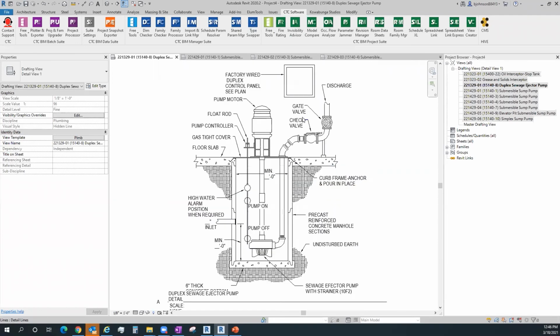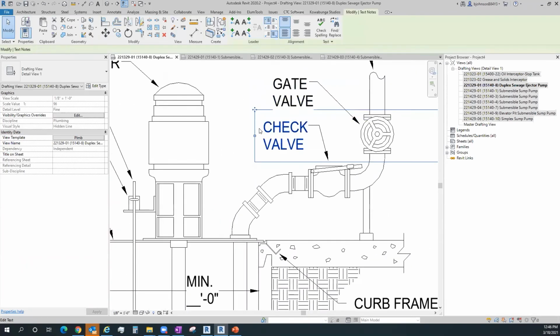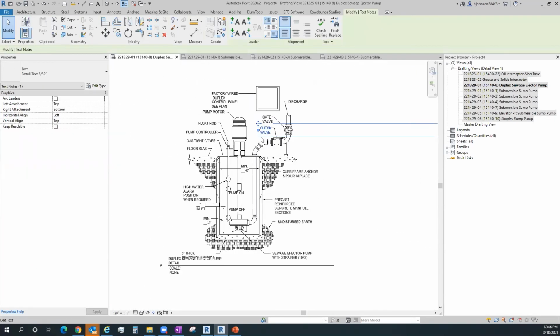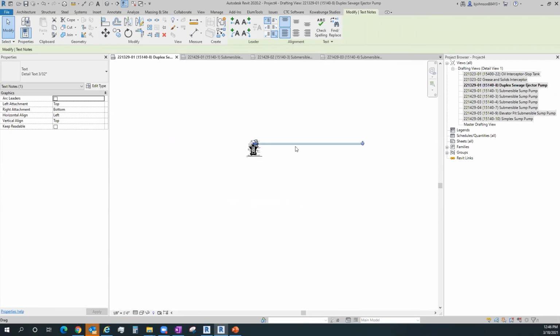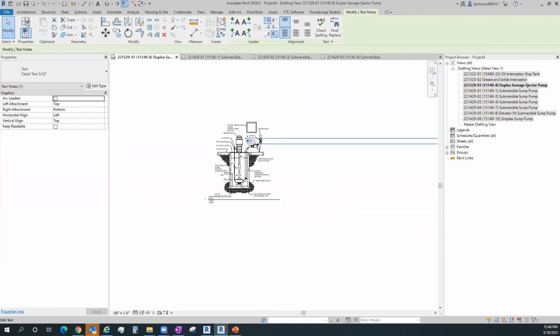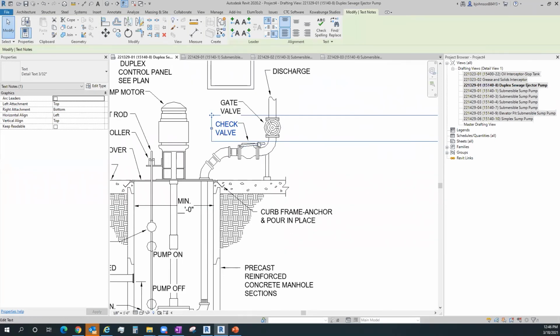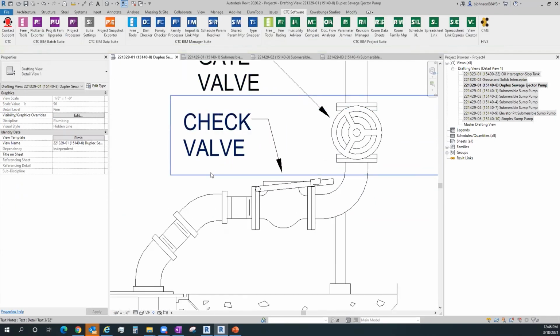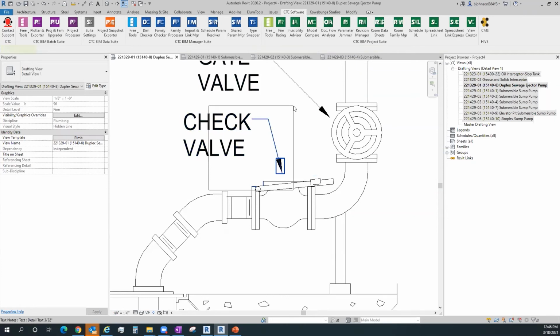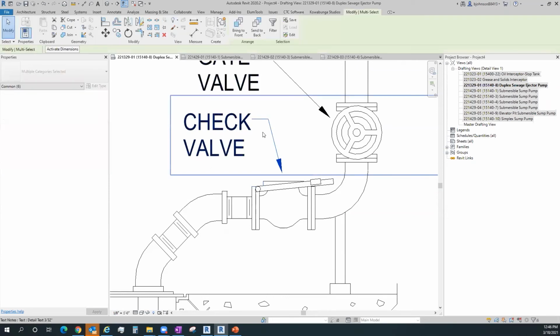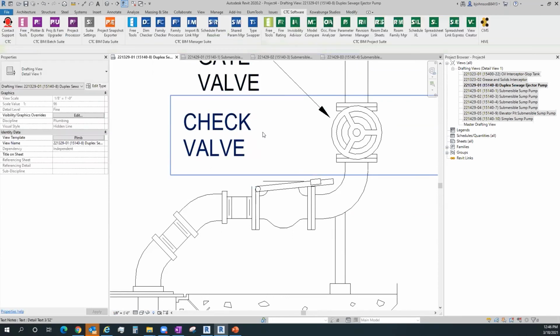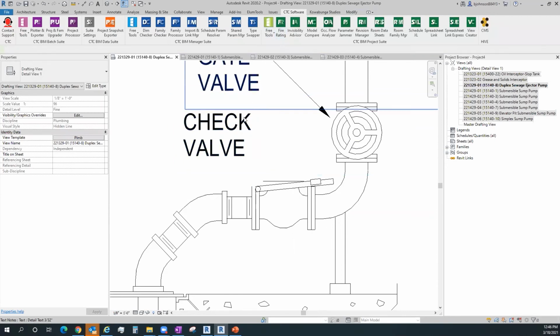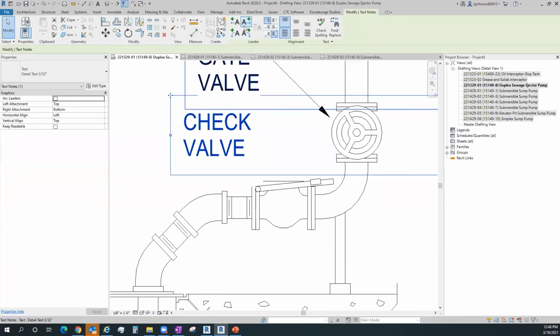So the last things I need to do on each of these would be on each individual component of mtext. I would go back and make sure that this large, long window that I typically despise, stretch it all back to a normal size, or just copy and paste it into a new piece of text, move it back where it goes, and then go find my line work and my arrowhead and actually do the delete on that component, and then draw a new arrow off the side of this one.